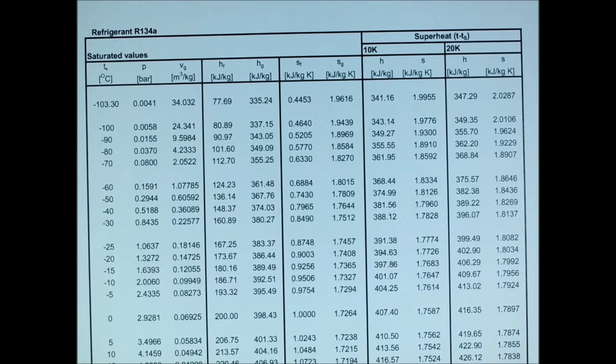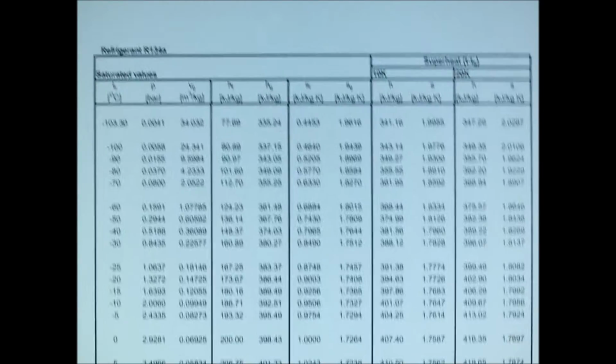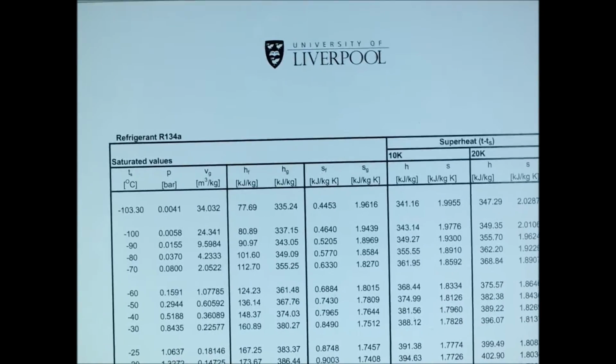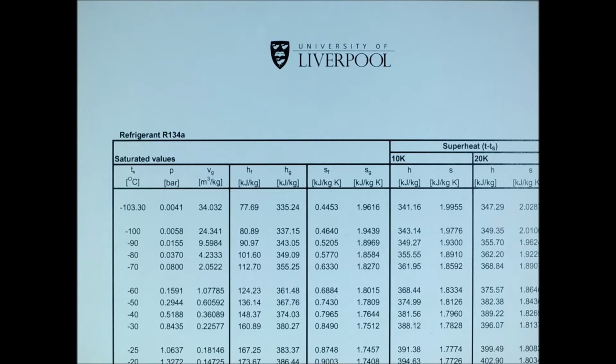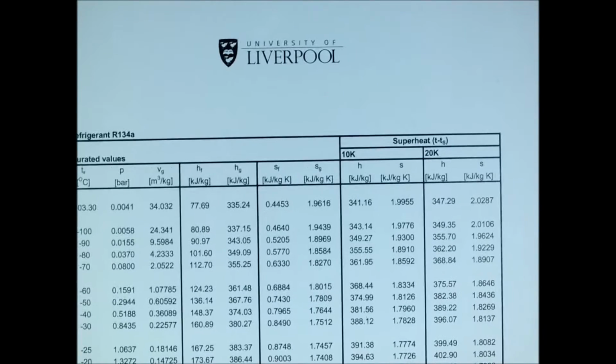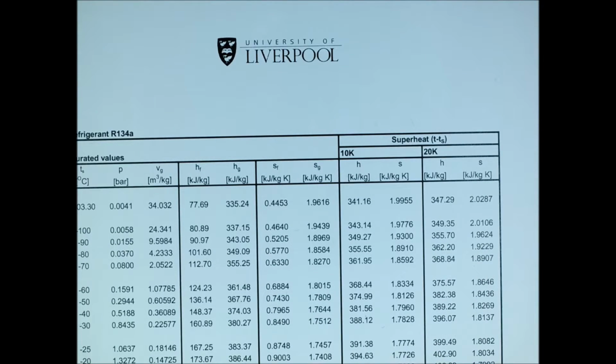But today I am going to walk you through specifically the table of the Hilton 175 unit, which we have here at the University of Liverpool, and this is its table. So what's different about it is the reference values that the manufacturers used when they compose the table. So if you decide to use this table with its numerical values, the results on another machine would most probably be wrong.